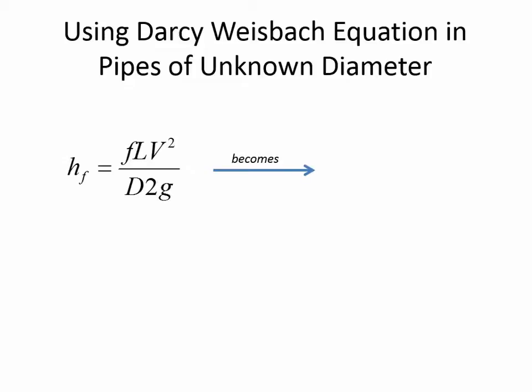If you've got a small head loss, then you're going to need a bigger pipe. But if you've got your origin tank really, really high in the air, which means you've got plenty of head loss to work with, then your pipe diameter won't need to be as big to deliver the same flow rate of water to the destination. Any questions about these expressions over here on the left? All right.